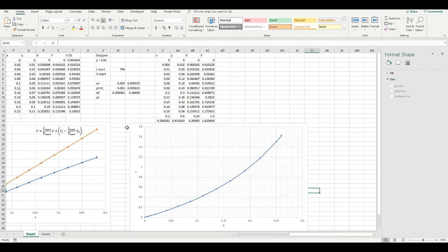And before I proceed, I want to say that this actually would be a perfect problem to use the Kremser equation if it weren't for the fact that the streams are concentrated, because this allows you to simply solve for the variable that you want. In this case, the flow rate. But now, since this is a concentrated system, we're going to have to use McCabe analysis, and since the number of stages is known, we will have to use a trial and error approach.